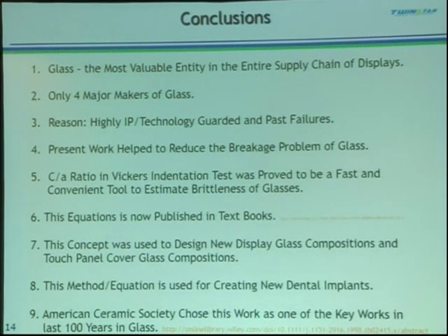The reason there are few glass makers is because the technology is highly IP guarded, and because of the past failures. Our work helped to reduce the breakage problem of glass, and this measurement of brittleness is very fast and convenient, and now it is published in the textbooks also. And then we could use this method to design new glass compositions, even for touch panel glass.